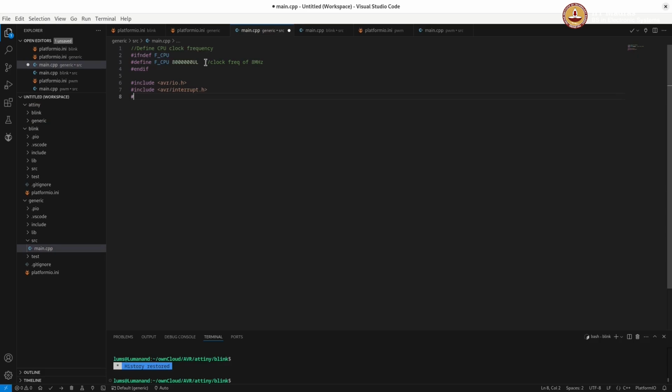And also include any other packages that you need. Right now I will not put anything. I'll just leave it at these two. Okay. So the includes will come at this point, all the includes. So if you are going to use the delay, you can use the util/delay.h at this point. But I'm not going to use the delay routine right now, so I will leave it at that.